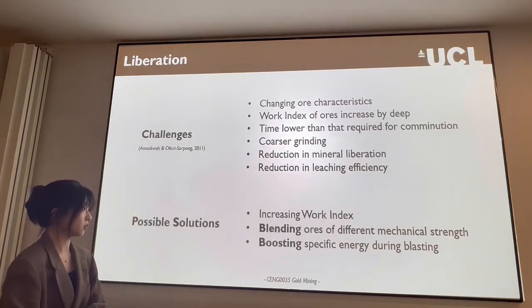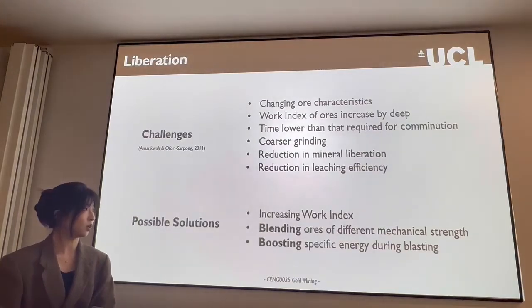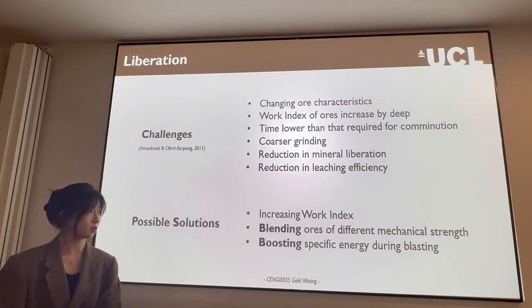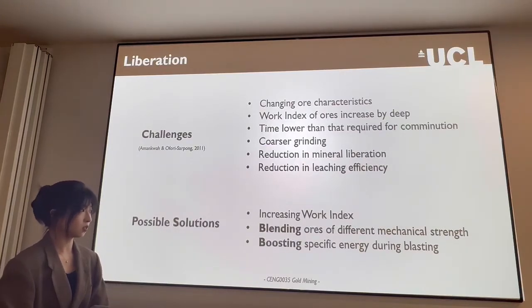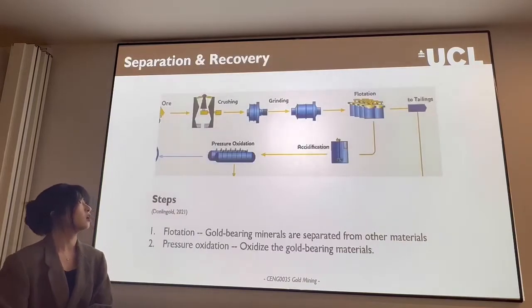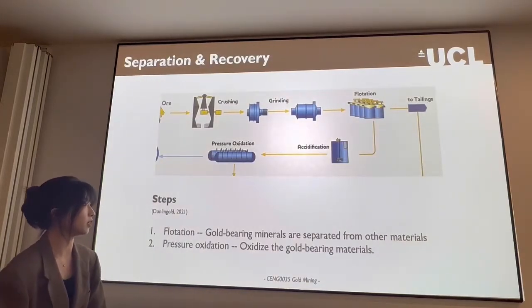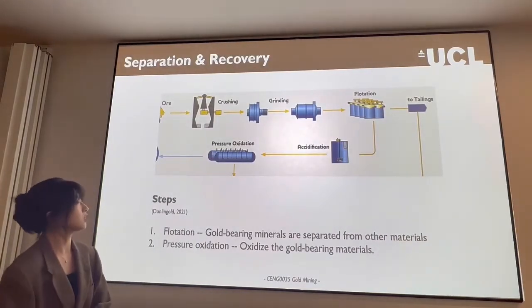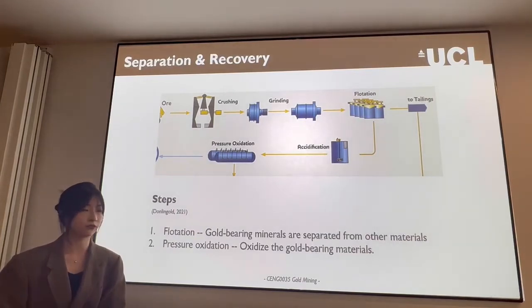Therefore, there are some strategies developed to address the problem of increasing work index. For instance, blending ores of different mechanical strengths and also boosting the specific energy during the blasting might be the possible solution. So the second stage of the gold processing might be the separation and also the recovery.